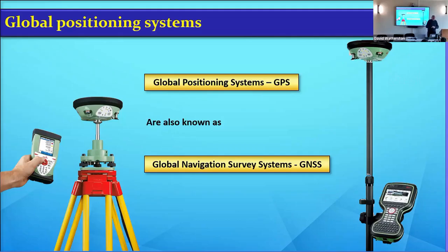The thing is with that once somebody goes and GPSes anything, if they go back in there 4 or 5 hours later and do the same job again, there will be differences. And the differences can be anything. It can be 100 mil, 200 mil, 500 mil. So you need to be aware of what you're doing with it, because it can give wrong information.